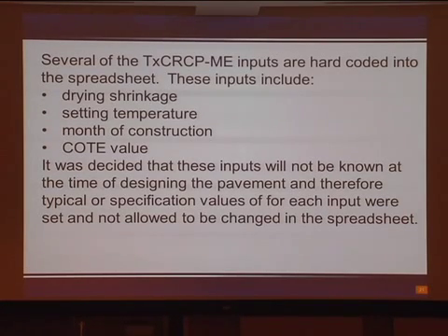Also, several inputs are hard-coded into the spreadsheet, including the joint shrinkage of the concrete, setting temperature of concrete, months of the construction, and the coefficient of thermal expansion value, because those values will not be known when you do the design.